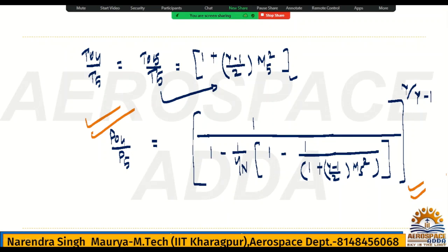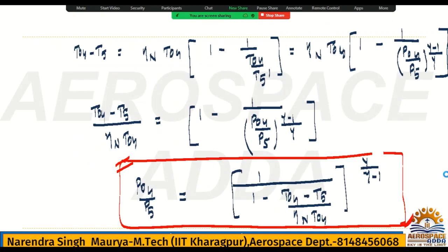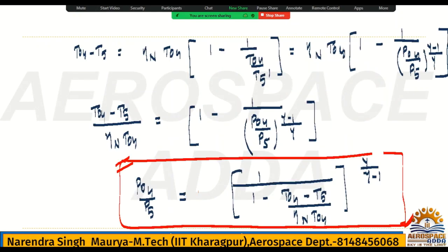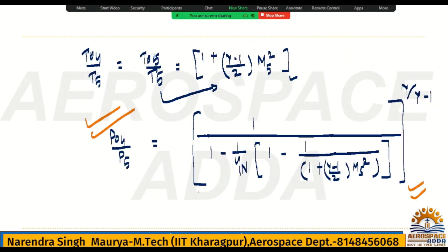But I am saying again, I want to write P04 by PC. So P04 by PC, this result you have seen, it will work, no doubt. It will work, but it will work when the nozzle efficiency is not given. But if nozzle efficiency is given, then this P04 by PC formula will not work. So that time what you will do? You can simply get P04 by PC in this formula only. Instead of M5 you just make 1.